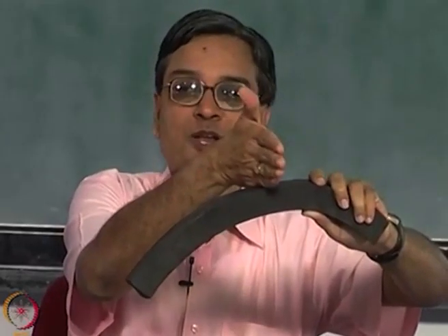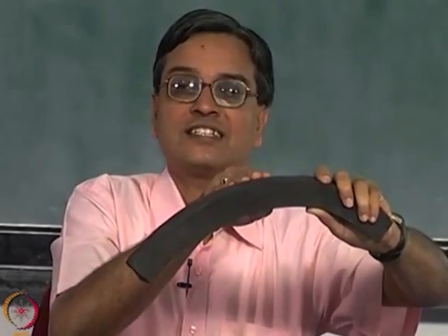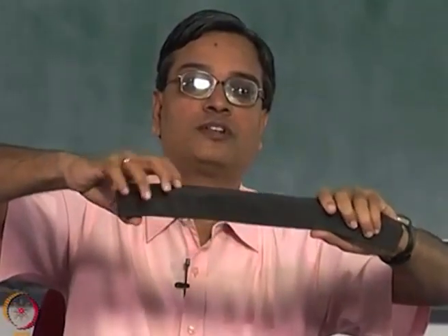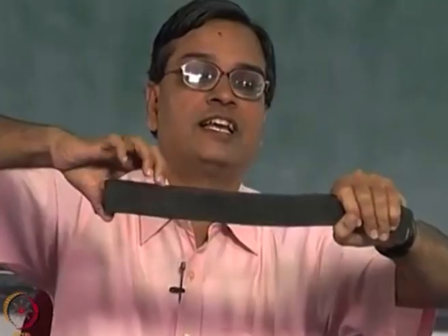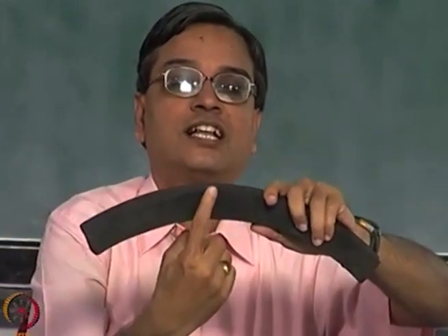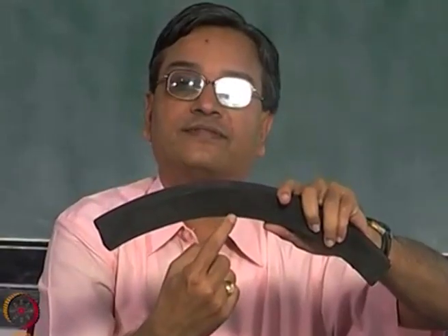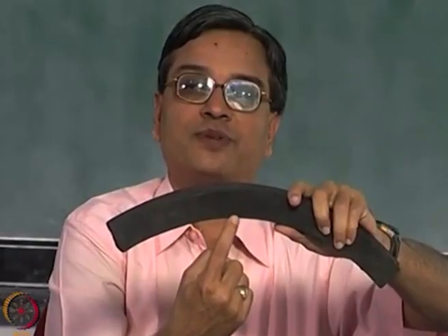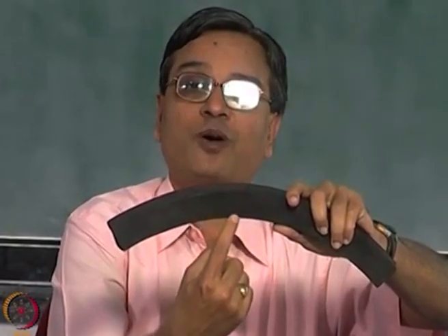Suppose I cut it perpendicular, I will have stresses perpendicular to that. So, it will be tangential to the boundary. And the other one, suppose I have this as a cantilever beam and apply an end load, I consider this as the fixed end and I apply an end load like this, it becomes like a cantilever, then I will also have shear. And in shear you have a parabolic variation. When you have parabolic variation, top fiber is 0 and bottom fiber is 0. Why do you say the top and bottom fiber is 0?